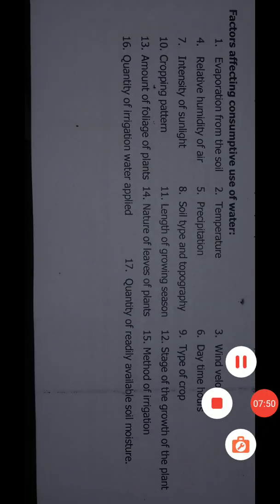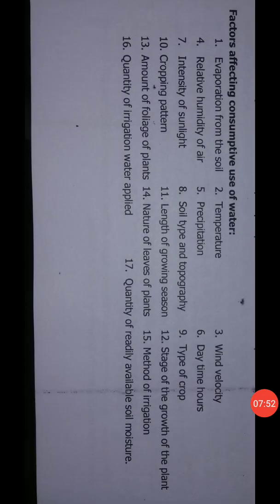The second one is the tank or lysimeter method. Tanks are watertight cylindrical containers which are open at one end and are set into the ground with their rim approximately flush with the surface. The tanks are 1 to 3 meters in diameter and 2 to 3 meters deep.